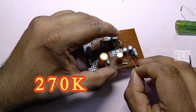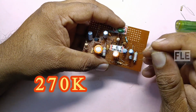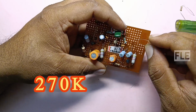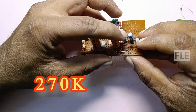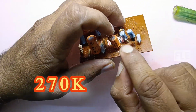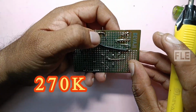According to the circuit diagram, a 270K resistor is placed between the base terminal of the second C1815 transistor and the 12 volts power supply terminal. The 270K resistor is soldered between the base terminal and the positive terminal. One end is connected to the base terminal.